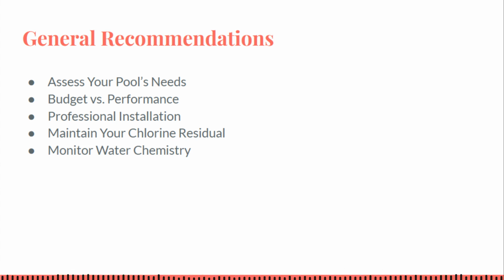General recommendations. Assess your pool's needs. Evaluate your pool's typical bather load and any water quality issues. If you occasionally notice chloramine odors or use the pool moderately, an ozone system will likely suffice to improve conditions. If your pool sees very heavy use, or if you have an indoor pool or family members with chlorine sensitivities, an AOP system offers the maximum level of oxidation and purification.